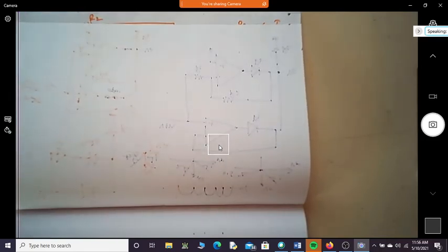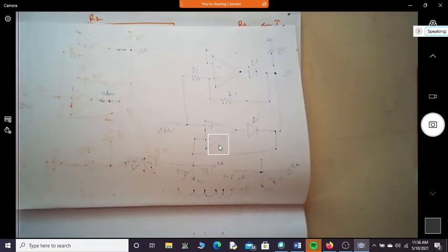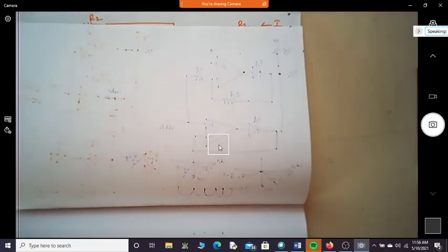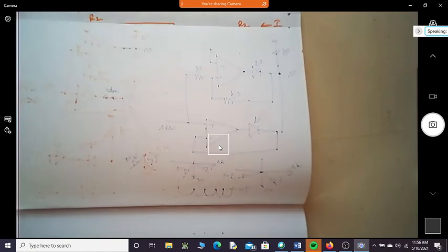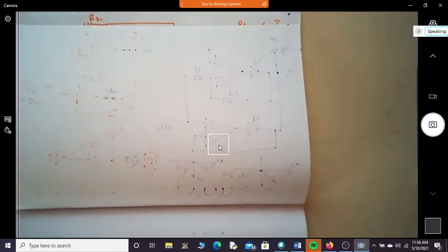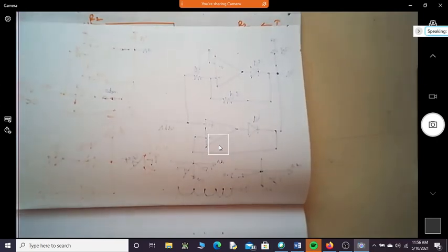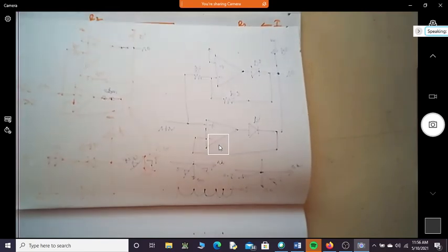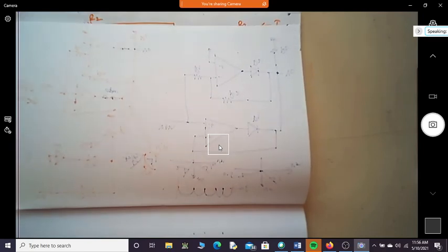Now, how do you relate the error voltage in PLL to the stable VCO that you already conducted? Suppose I say the error voltage is zero in the 555 timer, what is the control voltage then? You might have observed that if you don't externally give any voltage to the control voltage pin, what is the voltage? Is it always two-third VCC?